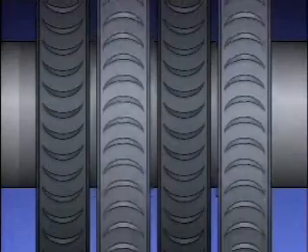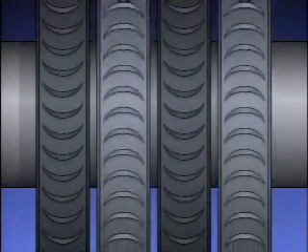Impulse blades work in a manner similar to the blades of a pinwheel. Air traveling in one direction strikes the pinwheel blades and pushes them out of the way, causing the wheel to turn. With turbine impulse blades, a similar thing happens. This simplified illustration shows the configuration of turbine impulse blading, with the rotating blades and the stationary blades or nozzles.